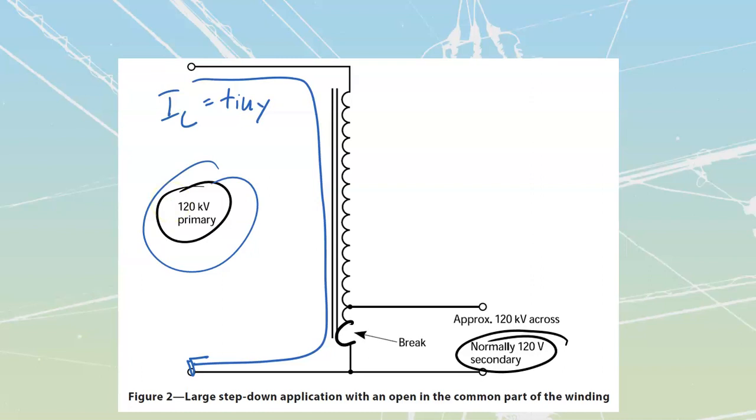Well, what happens with that line current is every time that line goes through a single one of these windings, it is going to be creating flux, and all of that flux is going to be dumping into this core. So we're creating all this flux through all of these common windings, and then, because energy cannot be created or destroyed, it can simply be transformed, all of that flux is going to get dumped back in over here, but across very few windings, which means that we're going to get a large amount of current.